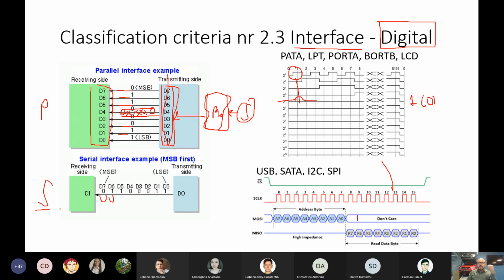So it's cheaper to protect only one wire than 8. So here we can raise the frequency to reach very high speed. Of course, in the serial interface we don't have only one wire, we have fewer, for sure. We have the clock, and we can filter or somehow protect this signal to not influence others, and protect, let's say, 2 or 3 wires.